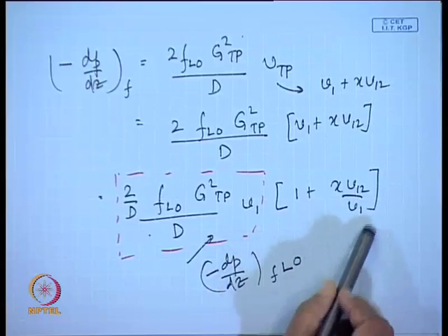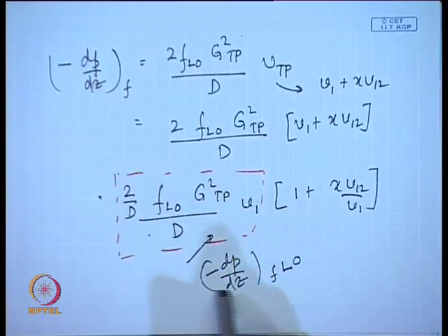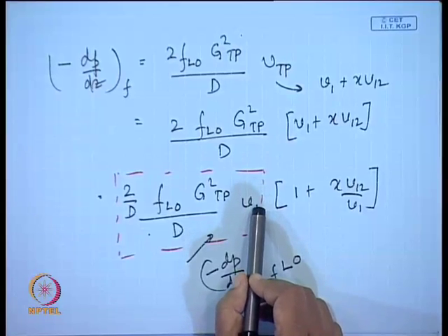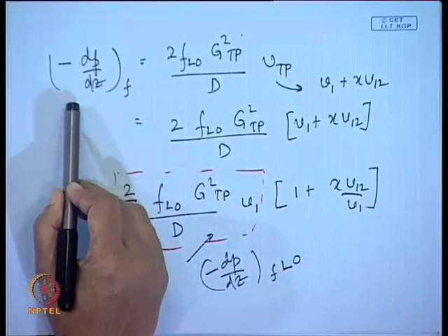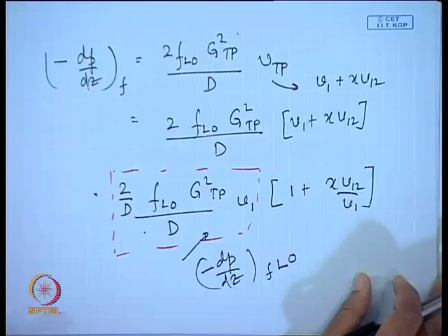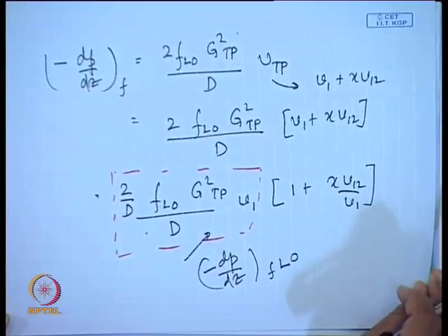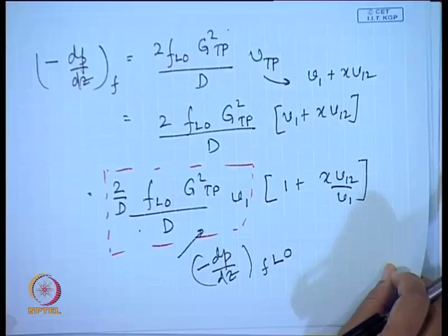Okay, specific volume is nothing but the physical properties. So, we can incorporate a suitable correction factor to the expression of the single phase liquid flow only pressure gradient, and we can obtain the pressure gradient for the two phase flow situation. Clear to all of you? When it was flowing as liquid, or rather when we were dealing with low quality vapor liquid flows.